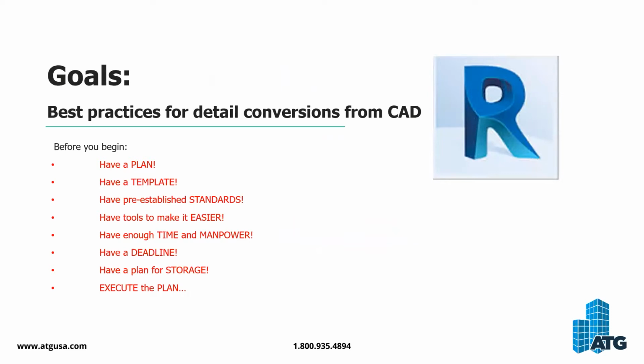Our goals today are best practices for detail conversion from CAD into Revit. Things that I want to challenge everybody to do correctly: number one, before you begin, have a plan, have a template, and have pre-established standards that match your standards in your real projects, right? If you have tools, they can make things a lot easier than doing it all manually.